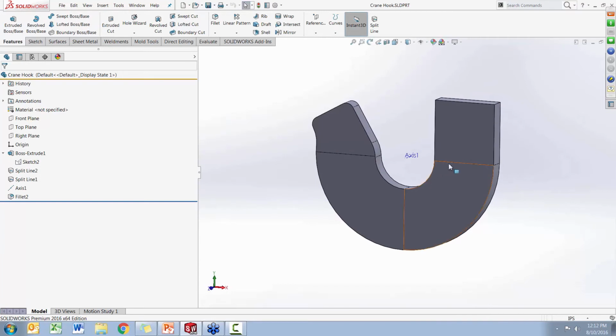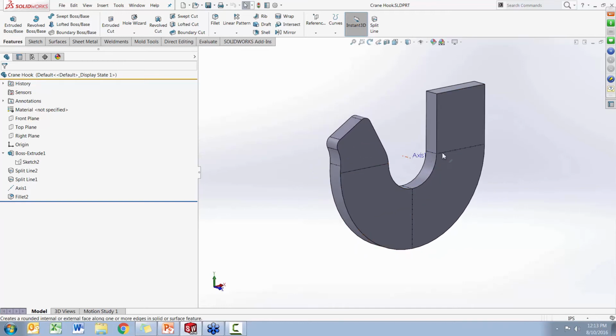I have these split lines created because I regard these areas as critical, and at the end of the analysis I'd like to study the stress distribution across these areas so that when I run the hand calculations I have something to compare against, and I can also use these sections to validate the structural strength of the beam.